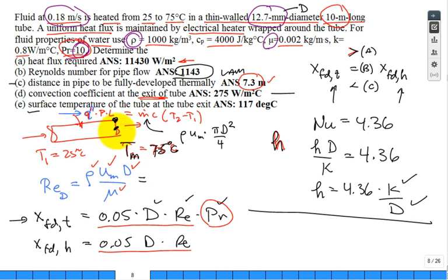So down here, just like right here, just like right here, just like right here, you're driving heat at a certain rate across the surface area into the fluid in the pipe. And so Q double prime at the exit is equal to the H at the exit, that's why part D was required, times the temperature of the surface at the exit minus the mean temperature of the fluid at the exit.